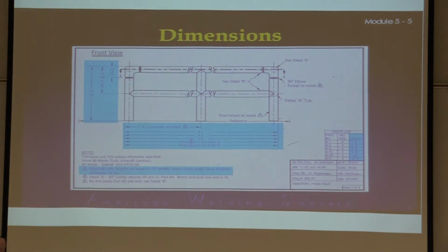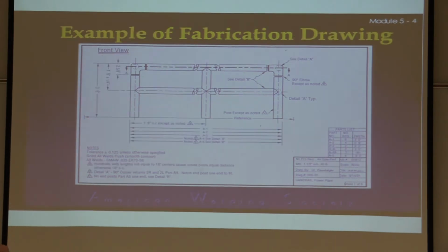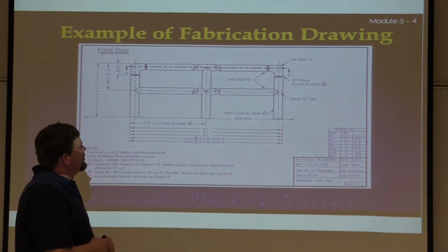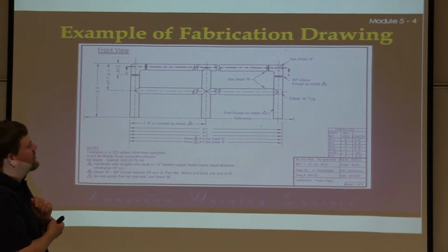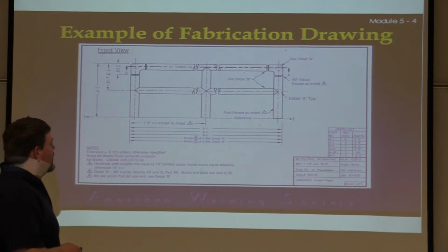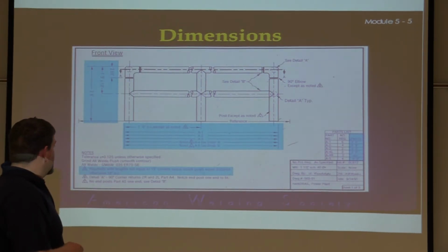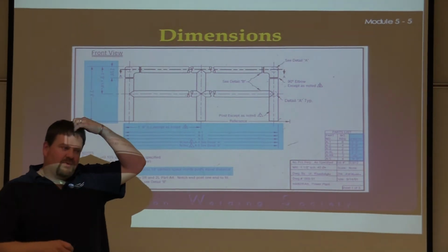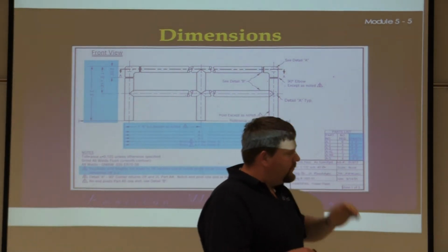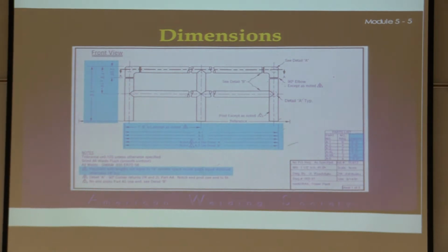We're talking about the dimensions. Now we come back in here and we start talking about the actual dimensions from outside to outside dimension. Some places will give you center to center, some outside to outside. Pay attention to those little details like that, okay? They make or break you in a lot of situations. Especially when it comes to handrails, you also need to know what the OSHA requirements are at the job, or if you're on a job site that requires MSHA, they may have more stringent specs as well.